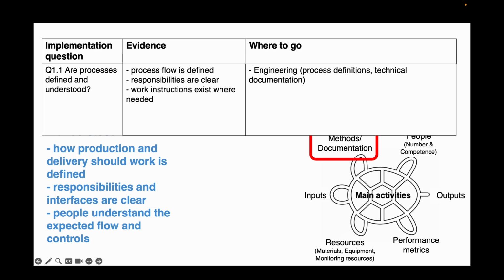Now, another place to go is quality. So in quality, I want to see evidence that the process is controlled and that the key quality points are defined. For example, control plans, inspection criteria, acceptance criteria, quality instructions, or documented checkpoints. Why? Because even if the operational flow exists, I also need to know whether the organization has clearly defined how conformity will be assured along that flow.